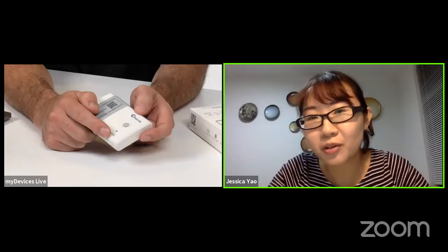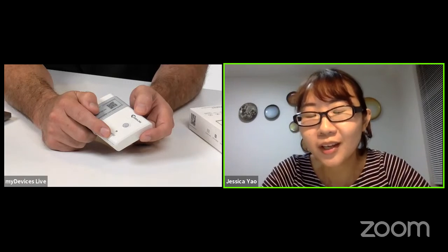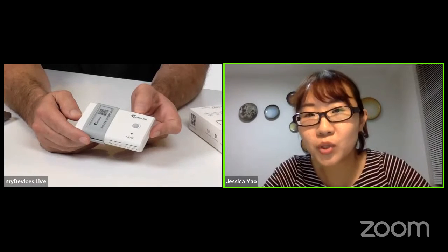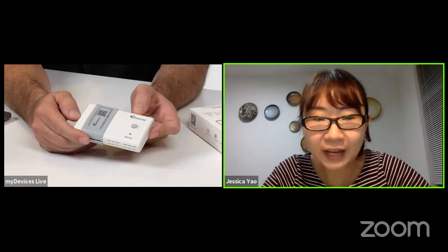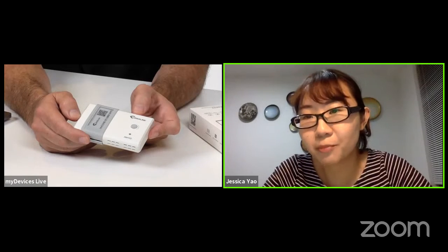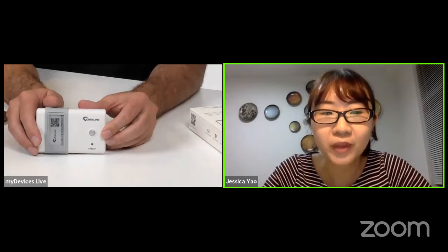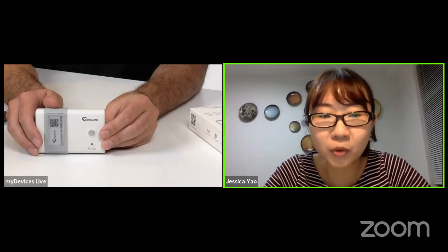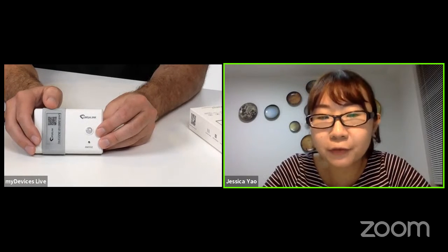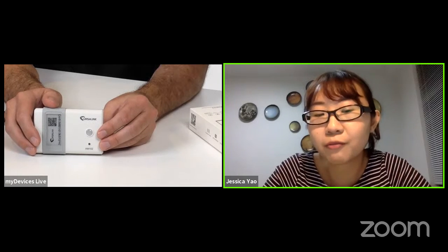Yes, because I think the other parameters, the temperature and humidity, are not so much related to the size of the room. But the personal activity, the PIR function, as Mona mentioned, is much closer related to the size. It can only detect motion within 94 degrees horizontal and 28 degrees vertical, and only within 5 meters.